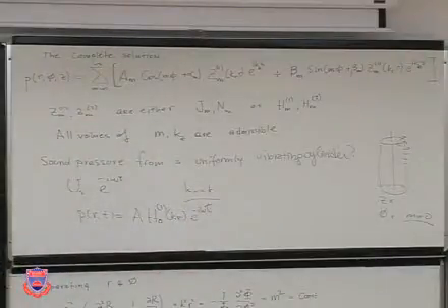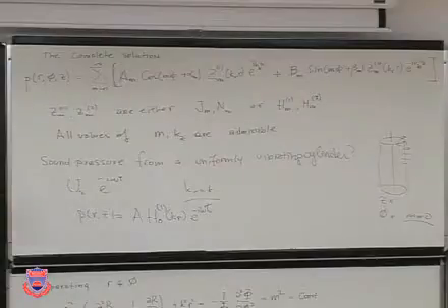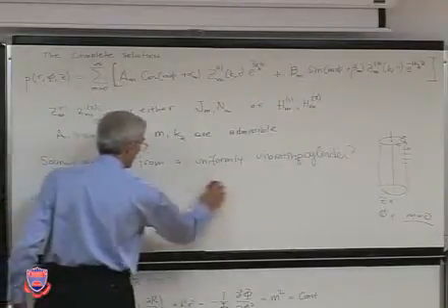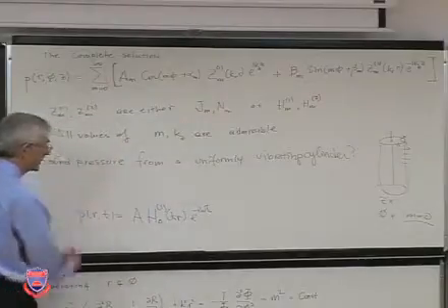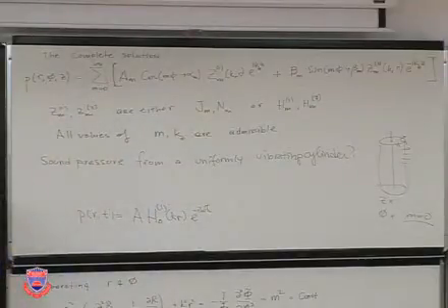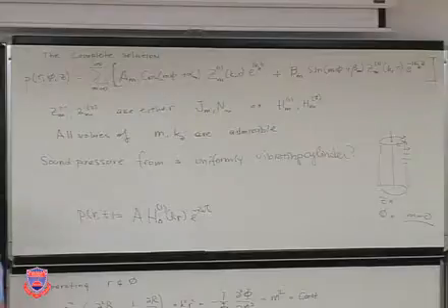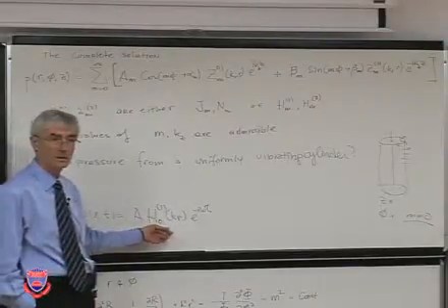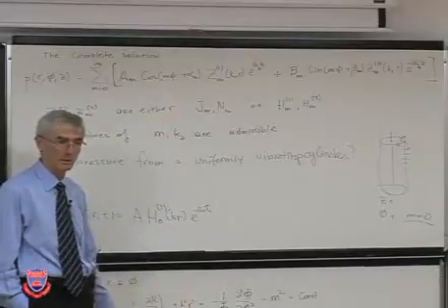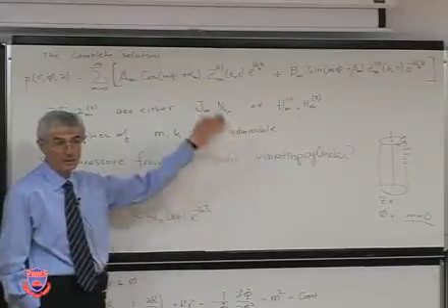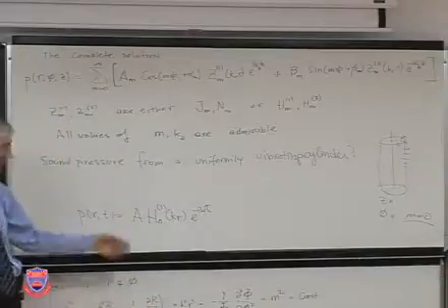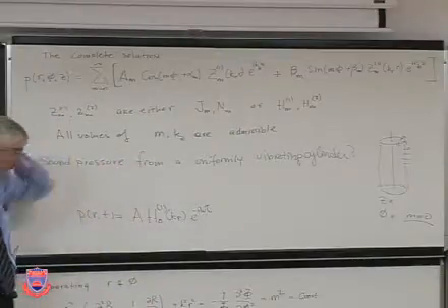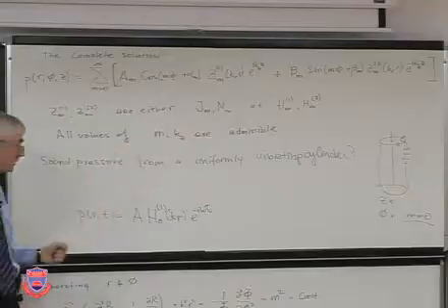And that would be the expression for sound radiation from a uniformly vibrating cylinder. It doesn't change in the z direction because we're assuming this is infinitely long in the z direction, otherwise there would be a z dependence. And it just radiates out.